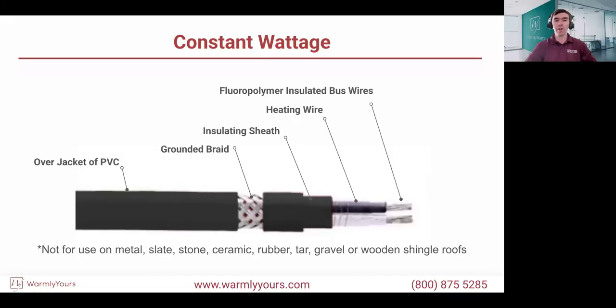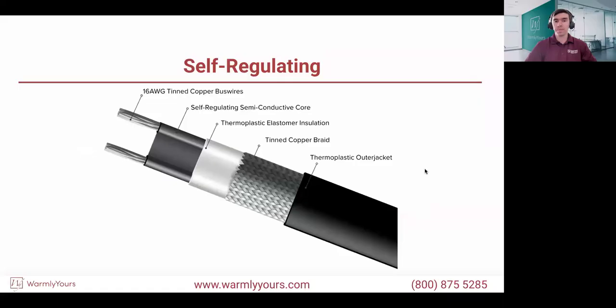So you should never be placing two cables overlapping, because you now will have a point of literally double heat being generated, and that can cause overheating and potential damage to the cable itself. That's where you simply apply the basic installation instructions technique to install the cable without overlapping and get your area treated as required.